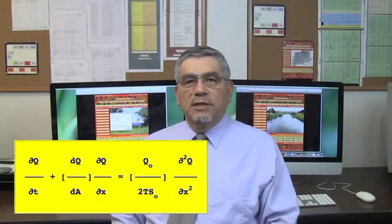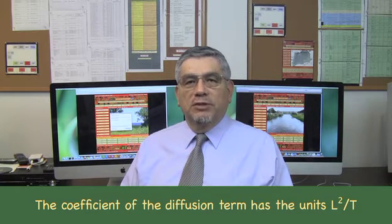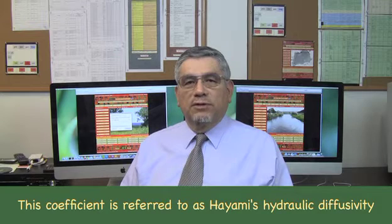The left-hand side of this equation is recognized as the kinematic wave equation. The right-hand side is a second-order term that accounts for the physical diffusion effect. The coefficient of the diffusion term has the units L squared over T. This coefficient is referred to as Hayami's hydraulic diffusivity. The hydraulic diffusivity is a characteristic of flow and channel, defined as follows.